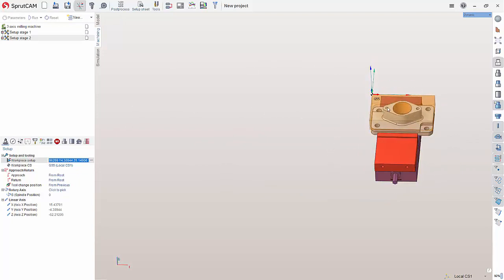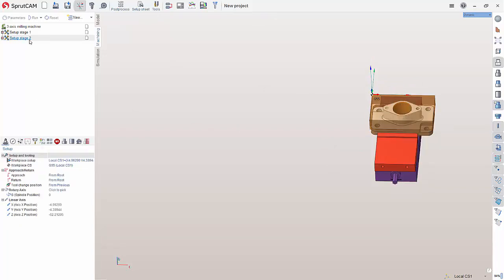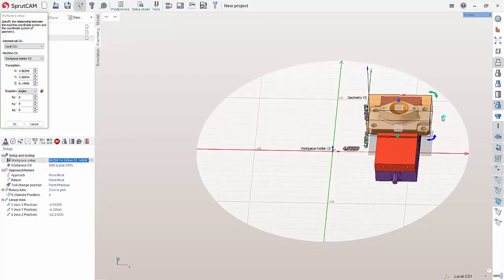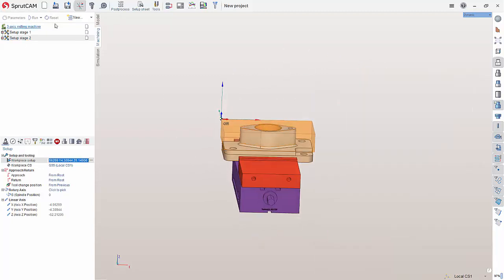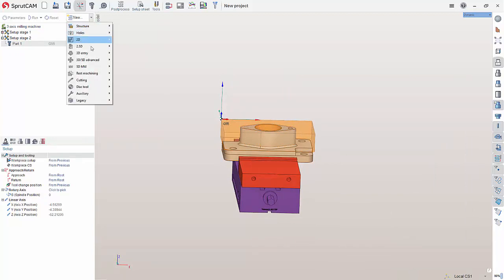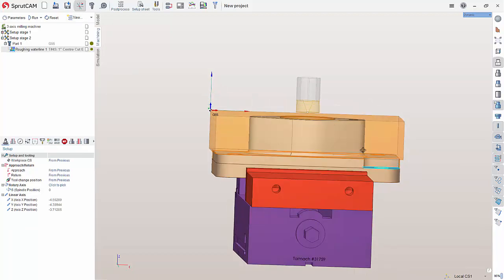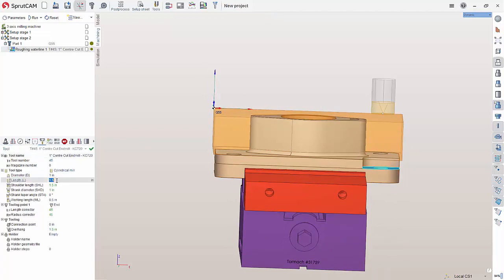And from there on, I'm going to go back in here and set this back to machine, and I want to actually move this over just a little bit next, just to grab onto it, just from a visual. All right. And then you can proceed to program your parts. So we could do a 3D roughing water line, say stop here as the bottom level. And then I'll just change the tool up again here. Let's see if we can get it right this time. A length of 3 and a working length of 2.